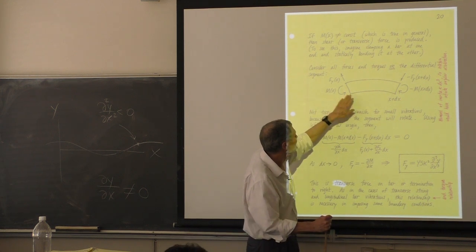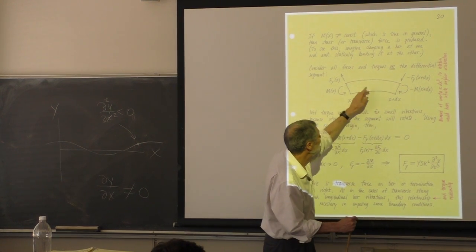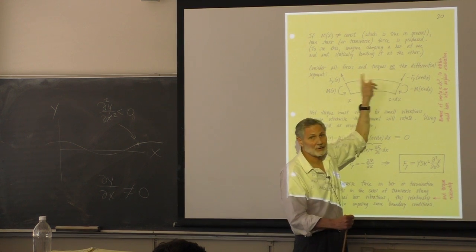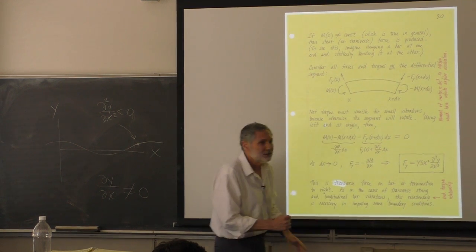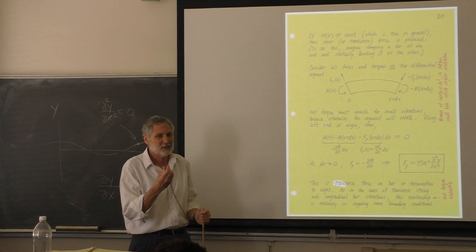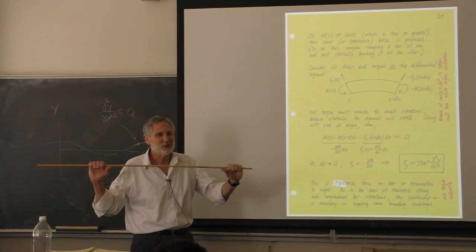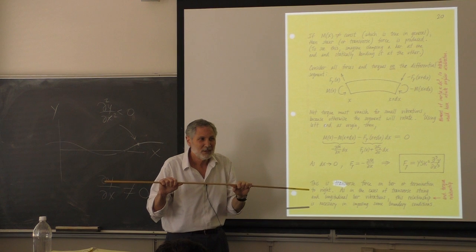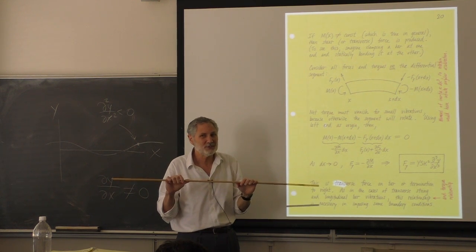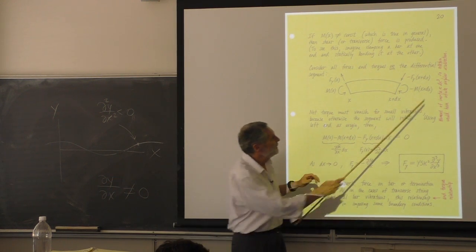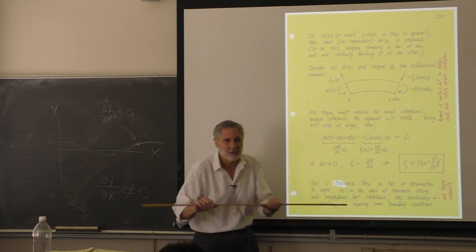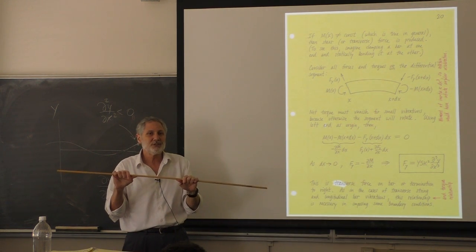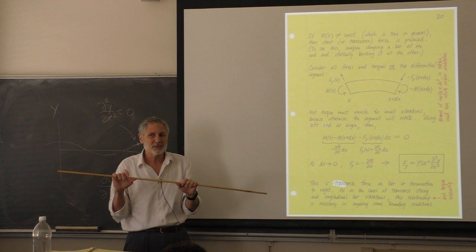We have torques here. We have a torque here, and depending upon our origin, these things can exert torques. What does the total torque have to be on a little element of a bar? You can probably guess. We're going to shrink this down to 0. The torque has to be 0. You can show this. And I made a comment. If you're interested, you can look at this comment right here. If the torque were not 0, we would have infinite angular acceleration.